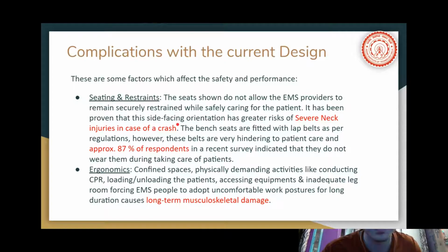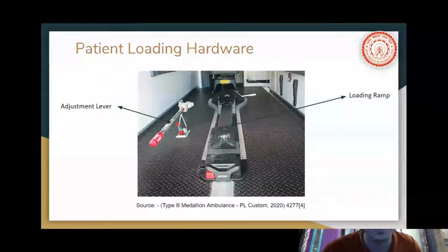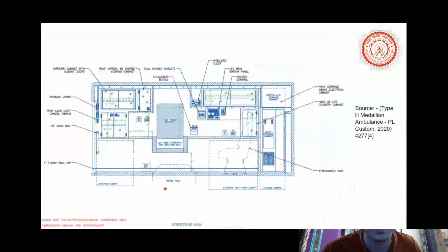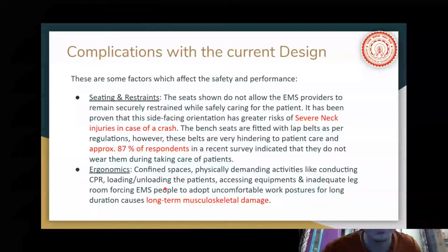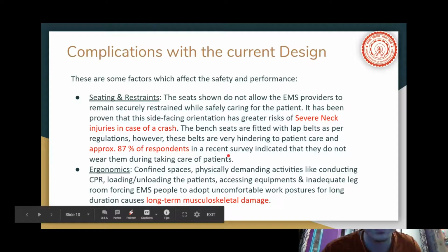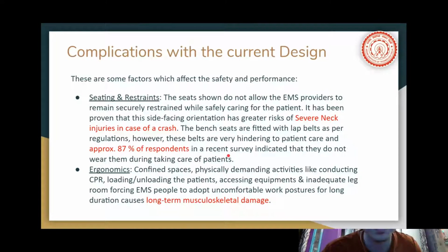One was the seating restraints. They pointed out that since the seating is this way, the two seating arrangements are sideways, and in case of a crash, this sideways arrangement can put the people at greater risk of severe neck injuries. Also, the bench seats are fitted with lap belts as per regulations, but these lap belts are so uncomfortable that 80% of respondents in the recent survey said that they do not even wear them during taking care of the patients.